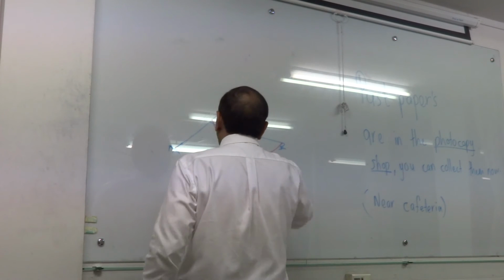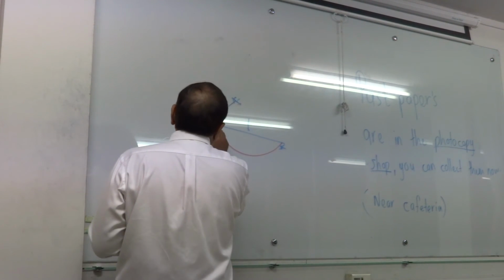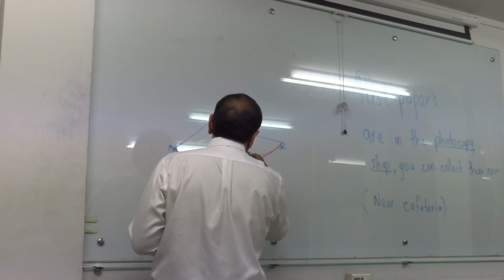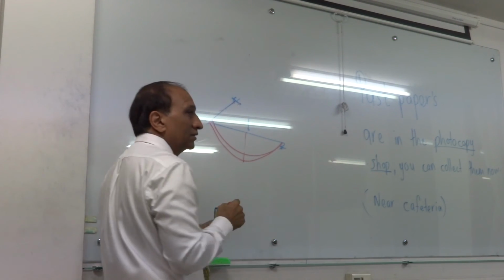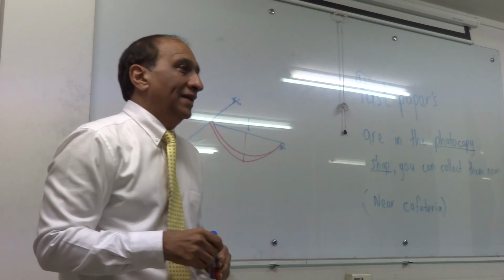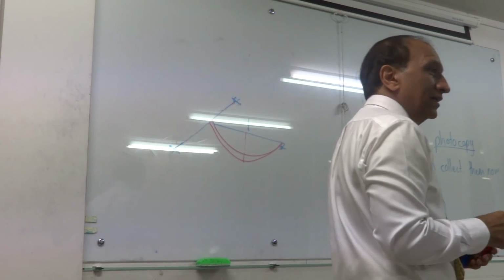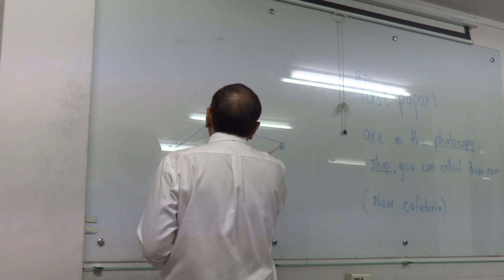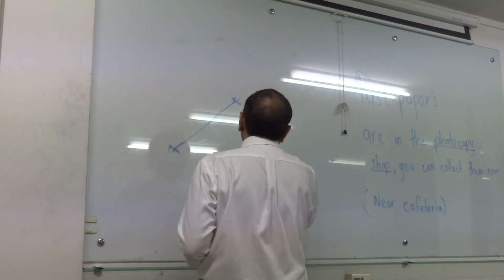capacity will disappear, and then this will rotate further, and this moment diagram will become like this. No negative moment anymore at the end, because that beam cannot take torsion. Or another way, let's think of another case.